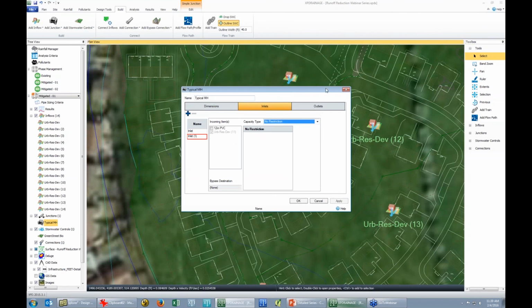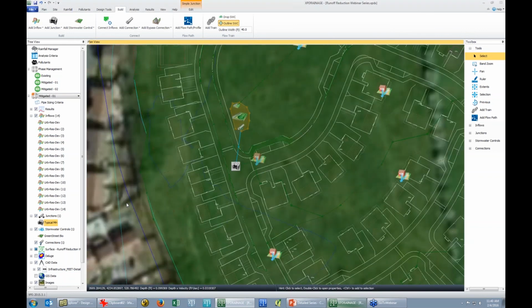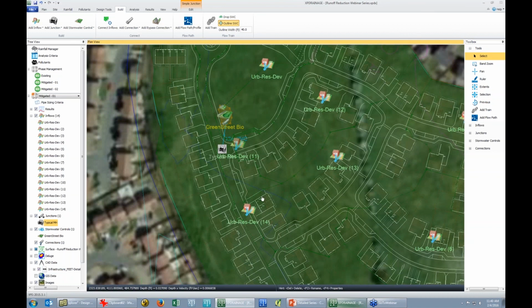So this is overland flow on the street. It's going to go through a grate. I could apply high, low bypass, a percentage restriction of flow. And then I could also specify there's maybe a pipe underground that leaves this manhole. There's also maybe an overland flow path. So all those items, in that traditional workflow using 8 different spreadsheets or tools, there's just no way that I could assess this. This really exists in the real world. We have to look at it, right? So pretty quickly we could see that we could add in, we could draw our facilities.